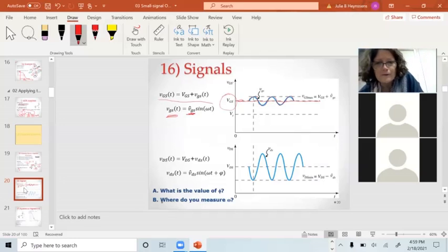And notice here what happens when this AC signal's at its peak, this AC signal's at its minimum, just like we argued in the last slide. If this one goes down, this signal goes up. And so what you're really getting here is a larger magnitude version of the input, but it's got a phase shift. And it's exactly 180-degree phase shift. Plus or minus 180 degrees doesn't really matter. You end up on the same point of the circle. And sometimes we just get rid of the phase shift and put a negative sign out front. It's the same thing.